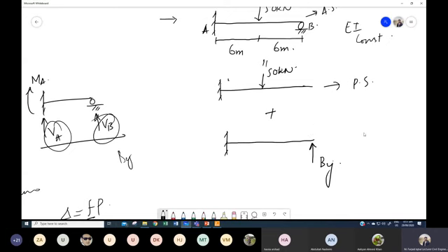In the case of reaction, it is usually in the upper direction, but it is not a fixed thing. But in the case of moment, usually things get confusing. So just apply the moment in any particular direction if you are taking that as redundant. And later, the signs of the final answer will tell you whether your assumed direction was correct or not.